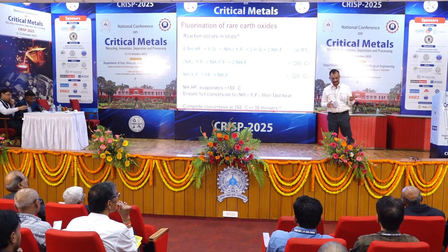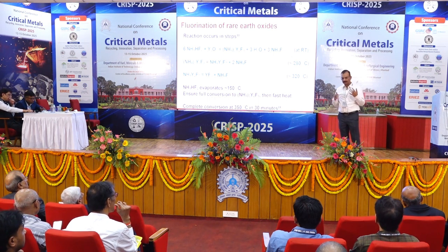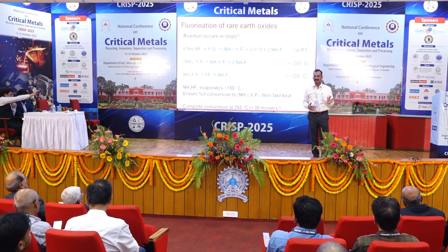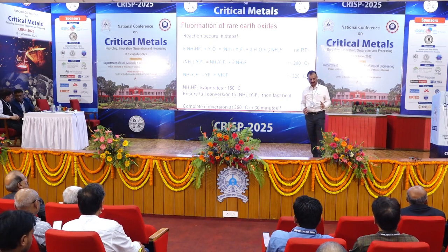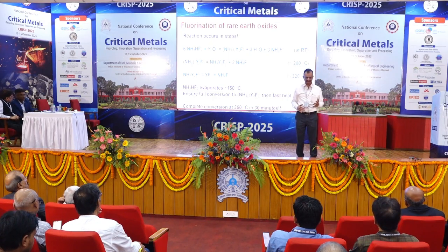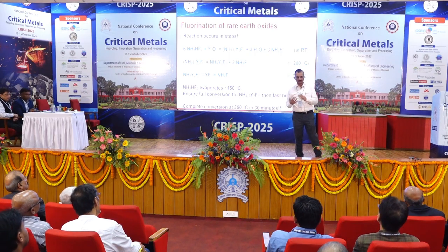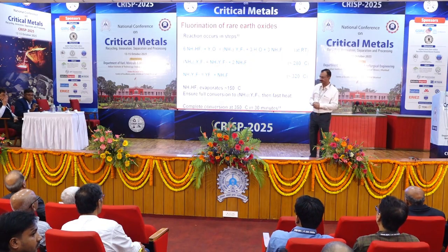So when you say extraction of rare earths from rocks, usually the percentage is quite low, in ppm, so you have to remove the gangue material anyway. You crush, grind and leach, and then do precipitation, and you bring it to some concentrated oxide or some carbonate, oxalate, a simple compound like that, and then comes the conversion to metal. Okay, I hope you are satisfied.